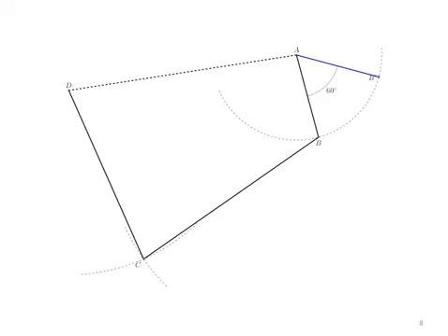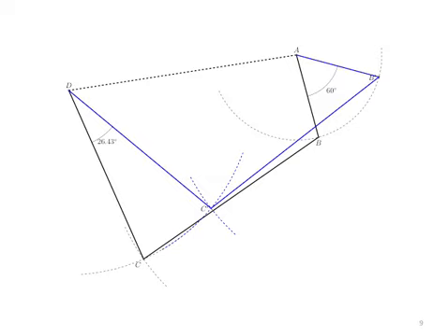Example of position analysis: rotate the crank arm 60 degrees counterclockwise. Determine the angle change of the wheel hub link. The length of each link does not change with repositioning. Point C' is located by the intersection of arcs from point B' and pivot D. Measure the angle change, 26.4 degrees, for follower link 4.